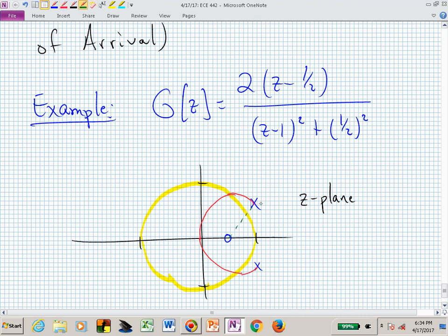But we're now trying to find what's alpha sub d? What's the departure angle? Which means that if I'm on this root locus a short distance away, here an epsilon distance, I'm basically right on that pole, but I want to be a little bit off so that I have an angle from that pole to that dot. All the other poles and zeros I can effectively be right on top of that pole. I now want to know what is alpha sub d. I want to know what is this angle, theta sub z, and what is this angle from that pole to the pole right above me.